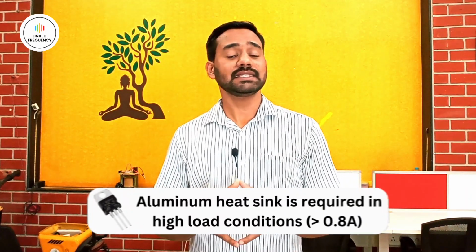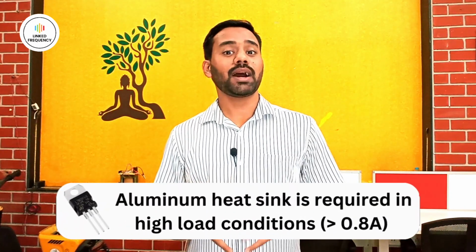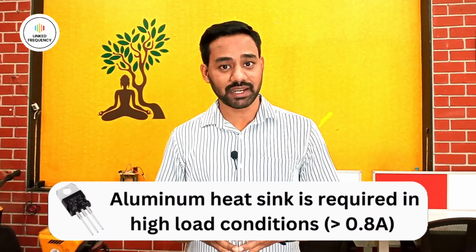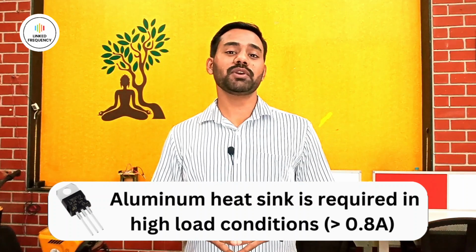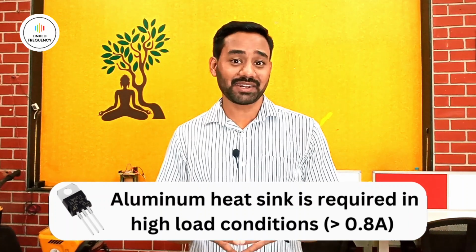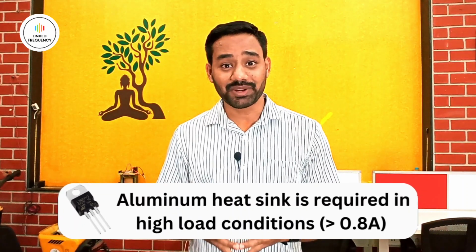Fourth one is this 7805 regulator requires an aluminum heatsink at the backside because when you are using this particular regulator for 1 ampere of current draw, it will get red hot up to 125 degrees Celsius. And as always, the typical application circuit and typical performance graph, all that detail is given inside the data sheet for your understanding. As per the requirement, you can understand the graph and understand the typical application circuit and use them for your application.